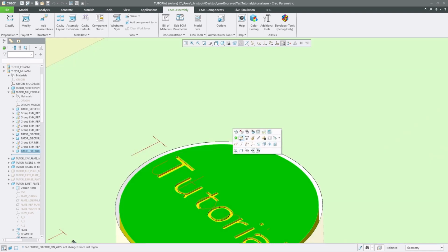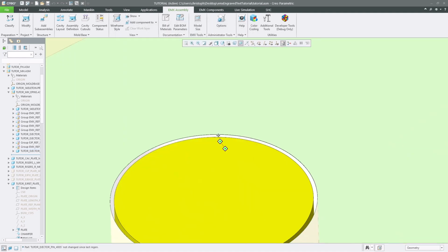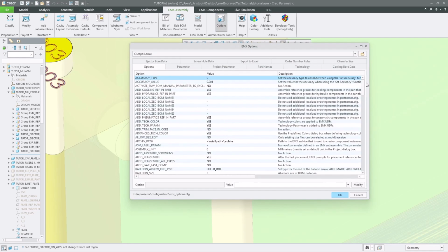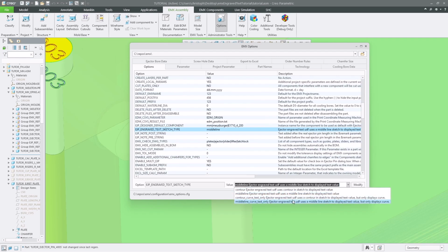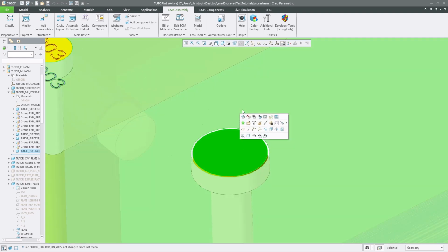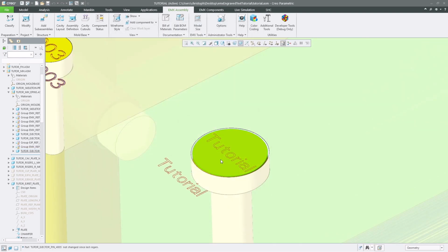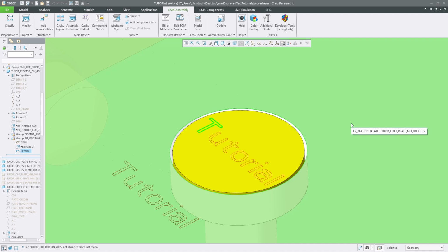Now, writing extruded text in Creo in general can reduce the performance quite a bit when you have many of these extruded text features. Hence, there are further sketch types available. If you set the type to Contour Curve Text Only, no extrusion feature will be added to the ejector pin or the plate. The text is written as a simple sketch text. So, the best course of action is to first find parameters that fit your Moldbase project and then apply the engraved text features to all the chosen ejector pins.